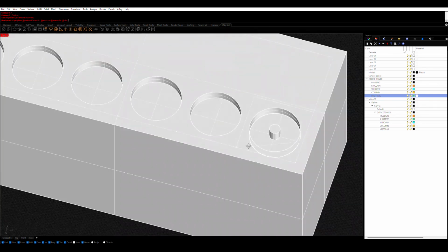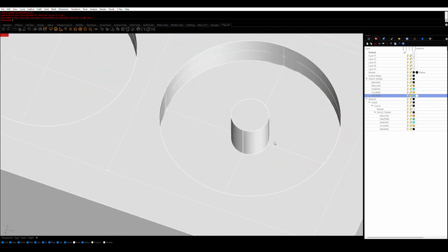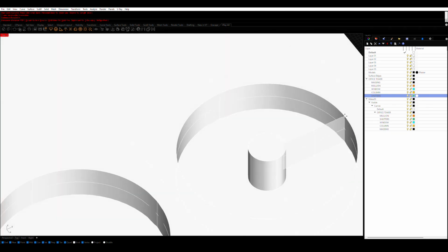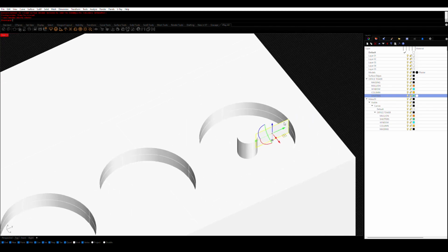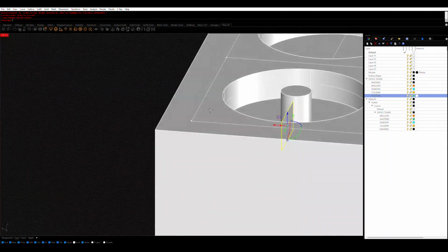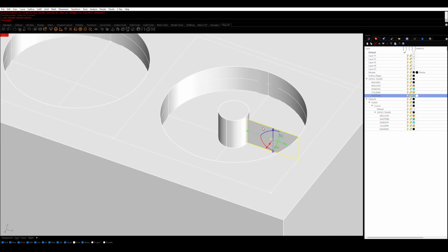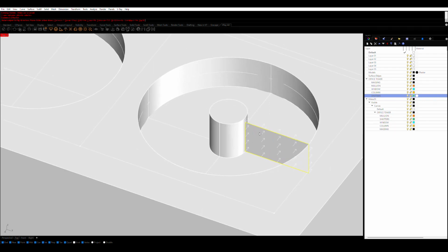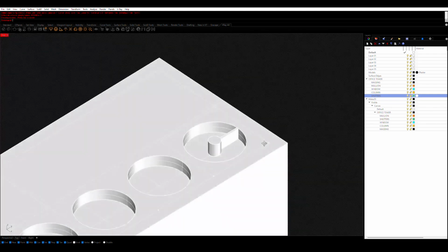And then from there, what we'll do is make a line. This will be our fin. We can raise this 12 inches, and from here, what we can do is use offset surface, and we can offset it on both sides, and maybe we'll just offset it by an inch, just so it reads in our drawing.